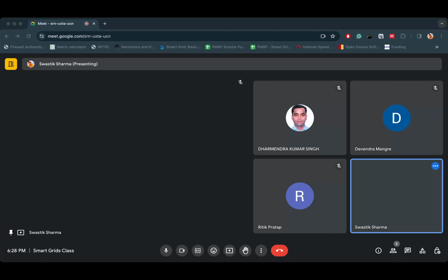Then this E bus is connected to this relay G, which is at G bus. This will also in turn have some positive sequence impedance. We'll add that. Then there are unbalanced loads connected to it, which we can denote by this, also a positive sequence load.